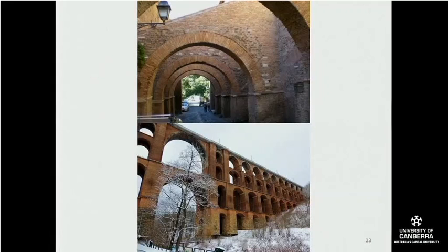It is also heavy, and needs a lot of energy for manufacture and moving. In certain circumstances, the bricks can get eroded, like when you've got a lot of moisture and a lot of salty air, like marine or beachside environments. You need to make sure that your bricks are properly fired. Otherwise, the surface of the brick, which is harder than the inside, can start to get eroded.